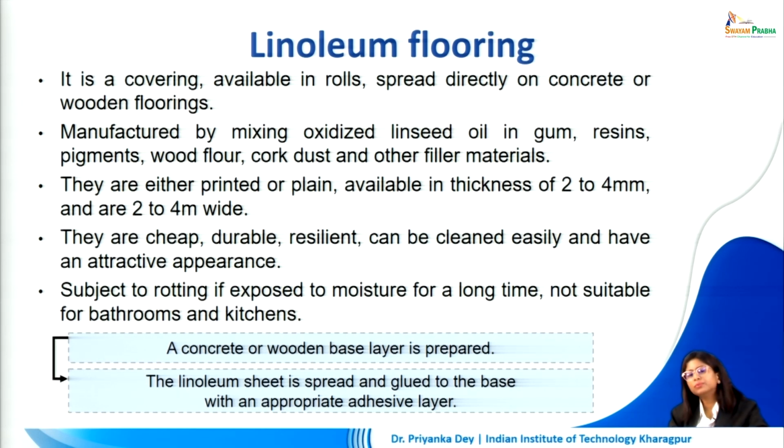They are cheap, durable and resilient and can be cleaned easily and provide a very attractive appearance because they are available in even printed versions. Subject to rotting if exposed to moisture over a long period of time. As a result, we do not want to opt for this in case of bathrooms or kitchen or utility areas. Here the base layer is topped off with the linoleum sheet, which is glued to the base with appropriate adhesive layer. So, in this case as well we require a very good adhesive.